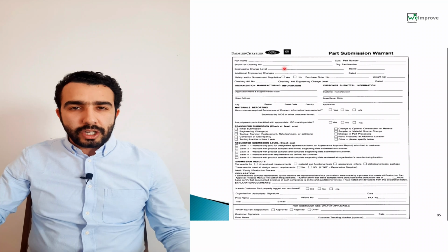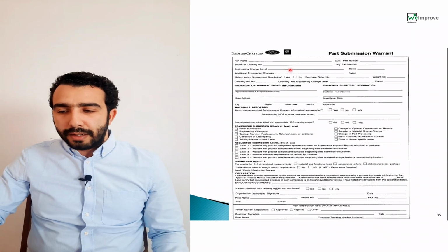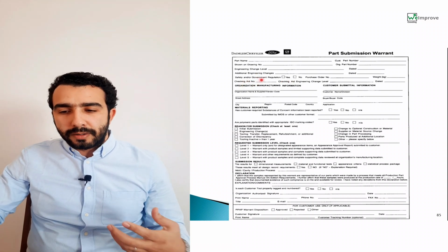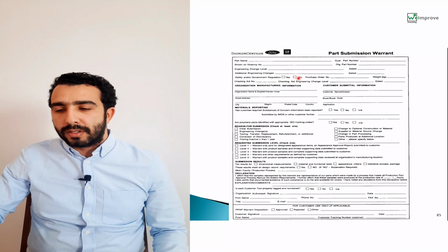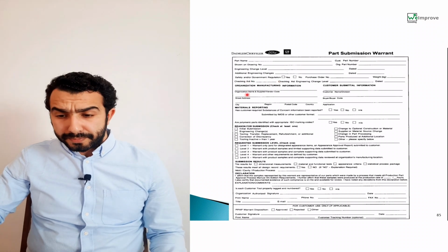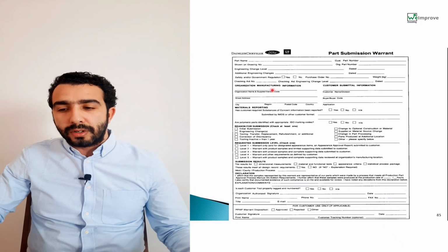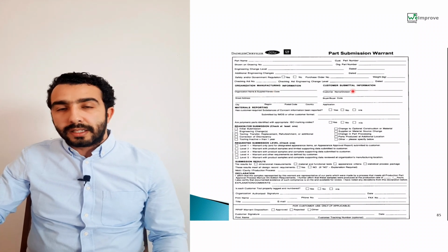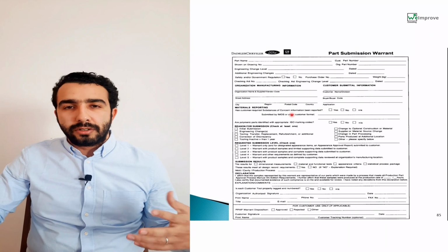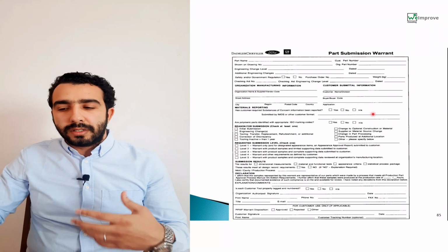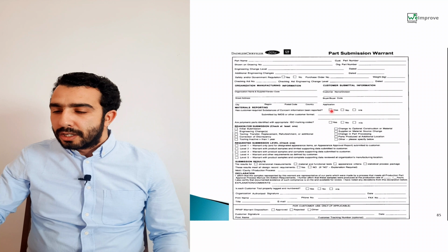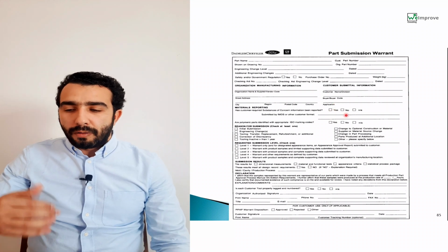Here, if there is any engineering change, any modifications, you have to put here the level and the dates. We have here, if for example your product is subject to safety and or government regulations, you have to cross here yes or no. We have here the weight of your product, the checking aids list. Here is all the information about your organization, and here all the information regarding your customer. Then here you have the IMDS, so you have to cross yes, because in general in the automotive industry, the IMDS is one of the most important regulation items. It's regarding the recyclability of your product. So we have to cross here yes, and put the number of the IMDS.